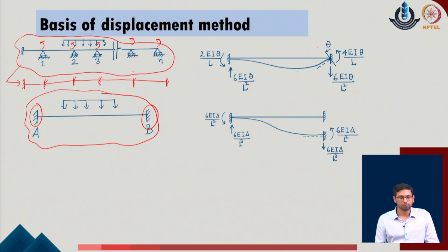Now, irrespective of the problem, irrespective of the loading, irrespective of the support condition, as many times as we try to solve a given problem, we will come up with only this condition of the kinematically determinate system. If any user wants to convert the given system into a kinematically determinate system, this is the only unique choice defined for the given problem, and this is also one of the basic differences between the force method and the displacement method.